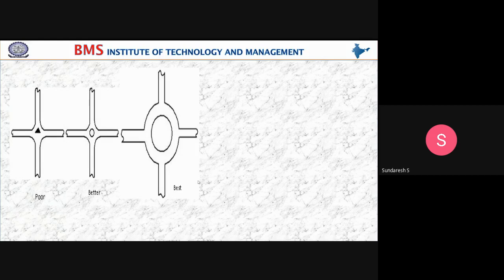Look at this, how they have done it. Instead of having sections like this, you will get hot spot shrinks over here. This is also very poor. This is okay. So make it like this. If more ribs come into the picture and they are going to join, then at the cross section make it a hole and leave it. We call these cored holes. This is the best way of designing components for casting purposes.